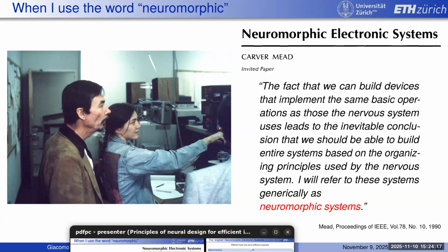But then if you look under the hood, like Terry was saying, of what they were actually proposing, they were proposing to use CMOS electronic systems. We're using subthreshold analog transistors. And in subthreshold, the transistor is producing current because of diffusion. It's called weak inversion, and the majority carriers across the transistor channel go from one side to the other because of diffusion. And if you know about sodium and potassium, and you know how action potentials are generated, it's exactly the same physics. You have Boltzmann statistics, exponentials, and therefore you can reproduce the same physics, even though it's a different medium, with CMOS transistors.